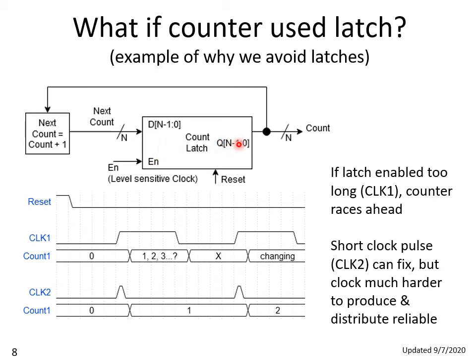Now the 0 will probably increment to 1, but as the count increases, the variation in the delay of the various bits will result in some garbage sequence. So in any case, you get unpredictable values, the clock is disabled, and now we've got a value of who knows what. It'll vary from one copy of the circuit to another. And then we re-enable the clock, and hereafter, the value of this thing is unpredictable.